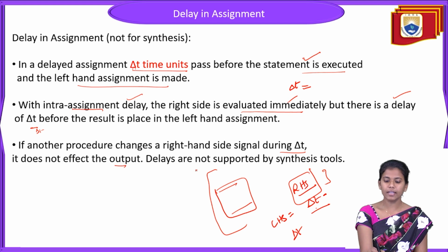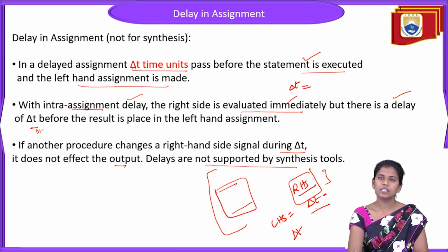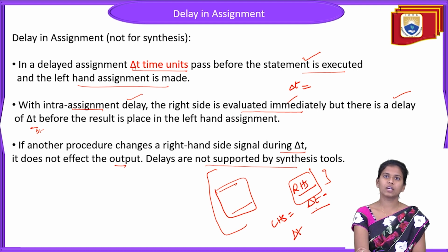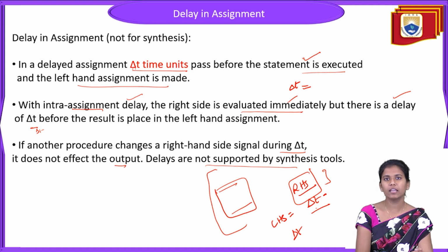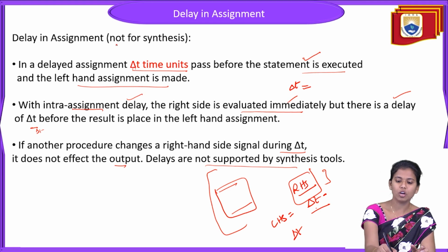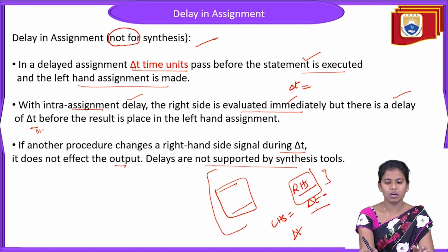Here the delays are not supported by the synthesis tool. For example, if you consider any kind of synthesis tool, delays won't be considered. So you see the delay in assignments only for non-synthesis procedures.